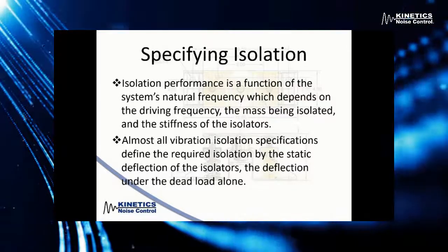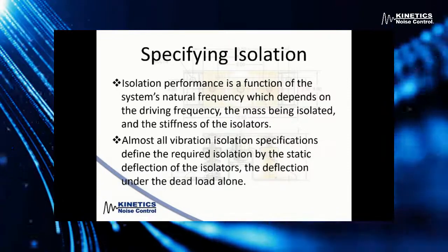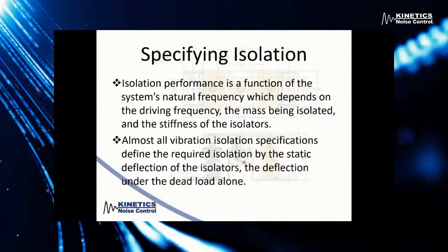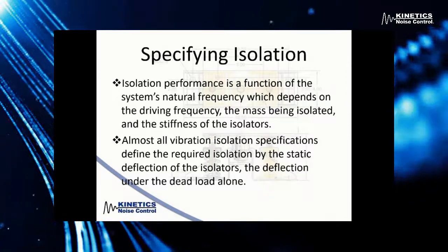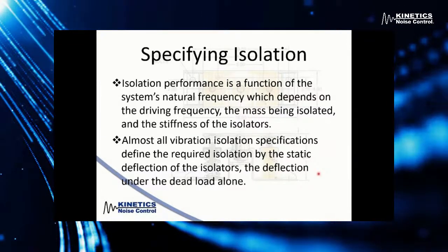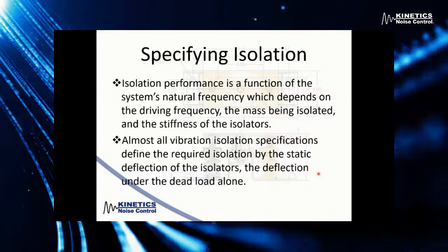It's not an isolator standing by itself. How much squish is going to be applied to the isolator once the weight of the equipment is on it? A lot of people look at vibration isolation like it's black magic, but there is actual science behind it when we look at things like the natural frequency and the driving frequency.